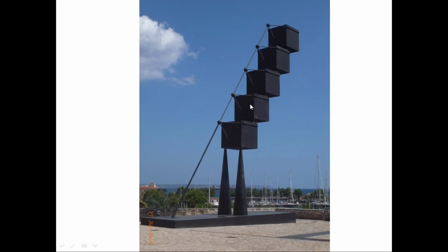So all the mass of the structure is going back down to ground here. But of course what's stopping it tumbling is this pure tensile element, which is way back here, where the mass of the slab is transferred, the energy is transferred, isn't it? So the pulling there is transferred into this mass, which possibly even goes below ground, I'm not sure, but if it was a continuous slab it would also work, because if you're pulling that way, the slab cannot deform in that direction.